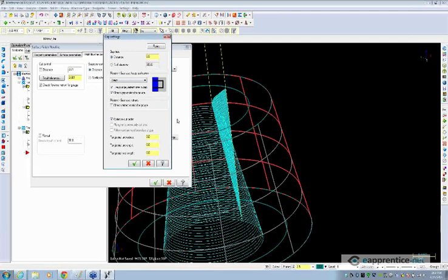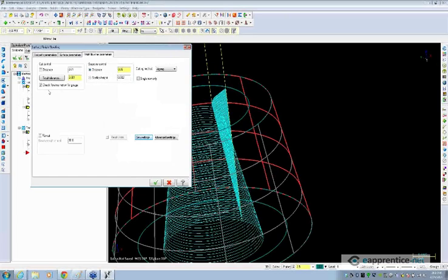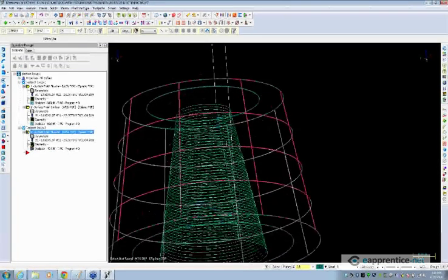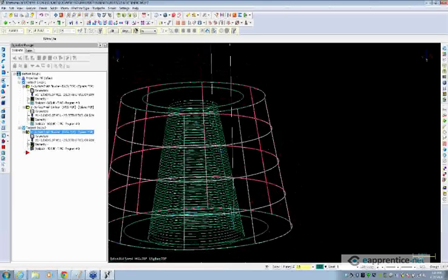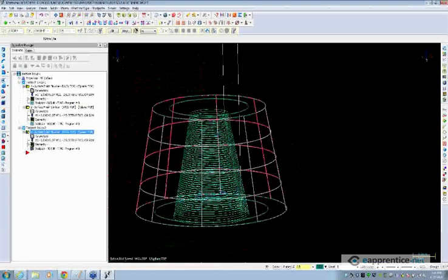Since it is just a tapered cone, we can go ahead and do a direct feed motion, and then turn off check gap motion for gouge. By turning off the gouge check, sometimes you also have to turn off this one here, check flowline motion for gouge, but we'll start with the gap. When you turn that off, that will now allow you to produce some nice, clean surface undercutting motion. And everything about this toolpath is great, except for the approach and retract. So we'll get to that in just a second.